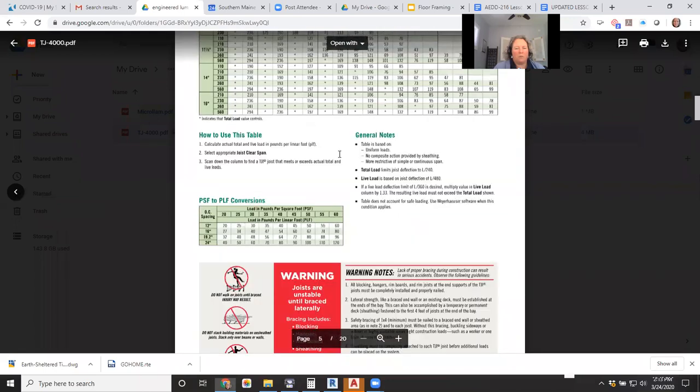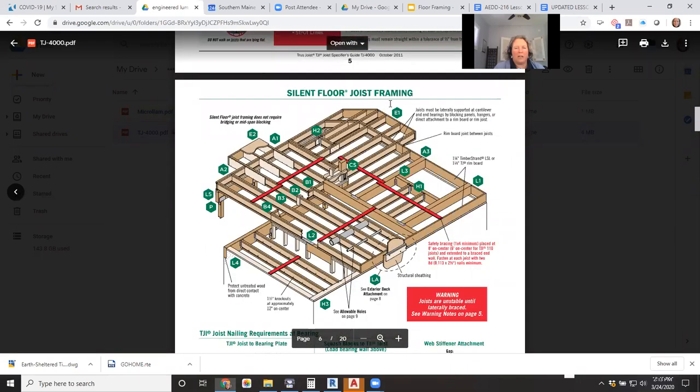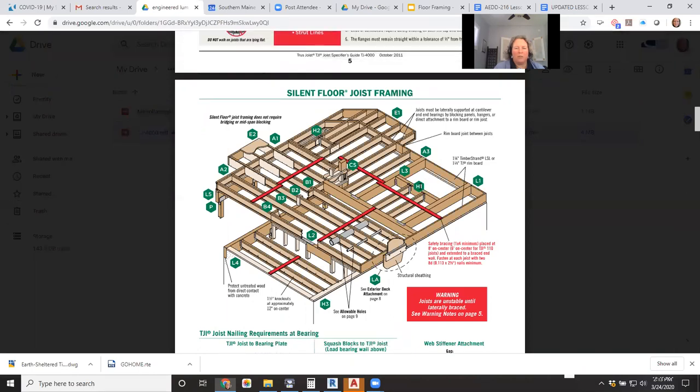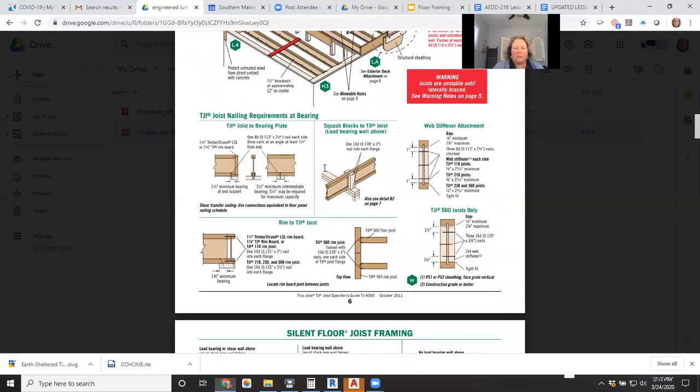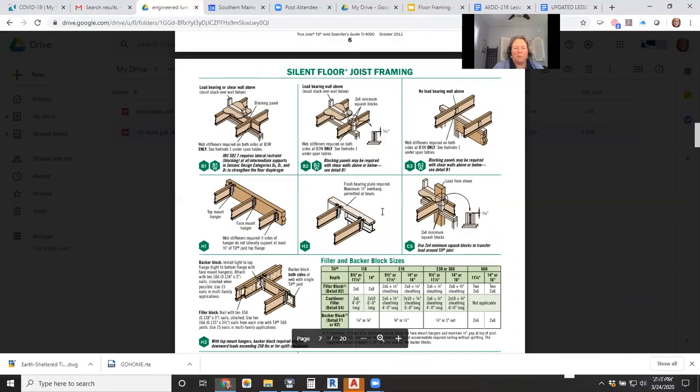documentation. If we scroll down to the area that shows sill and floor joist framing systems, it shows you how these things get put together and framed and what we might be looking at. So this is an example here of web stiffeners that would show up in between, filling in that web area to make it even stronger in certain areas. And I think they're doing that here because they're cantilevering a little part of the floor here. It shows you what kinds of cuts can happen in that floor framing system, and it shows you some connections and joints that you'd see, the typical ones.